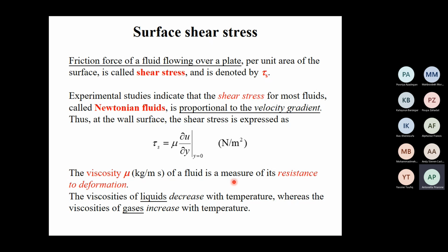So for example, if I have to size a heat exchanger from the thermal point of view to, for example, obtain a good performance from the heat transfer rate of my heat exchanger, I have also to analyze the heat exchanger from the point of view of pressure drop. Because if my heat exchanger is fantastic from the thermal point of view, but wants a pump of a lot of kilowatts because the pressure drops are very high, it is not a good heat exchanger.